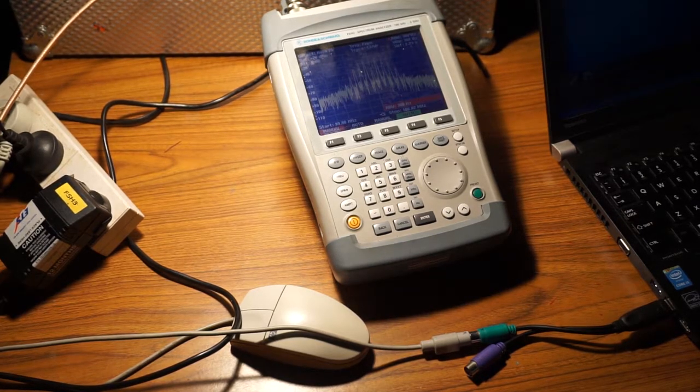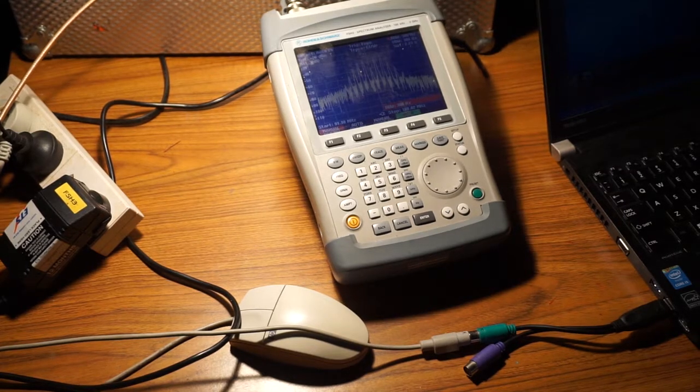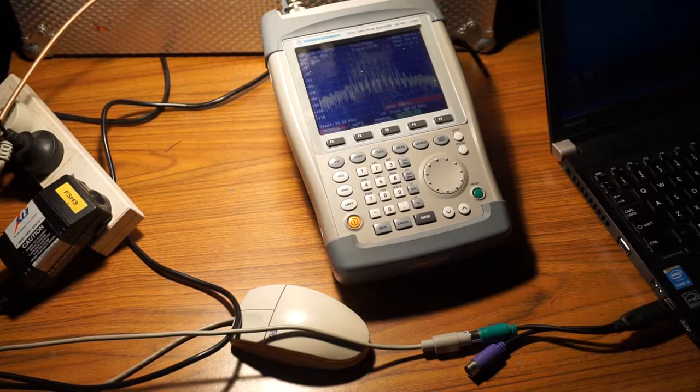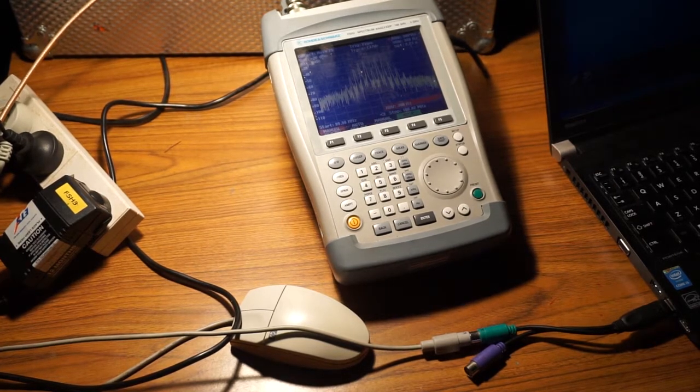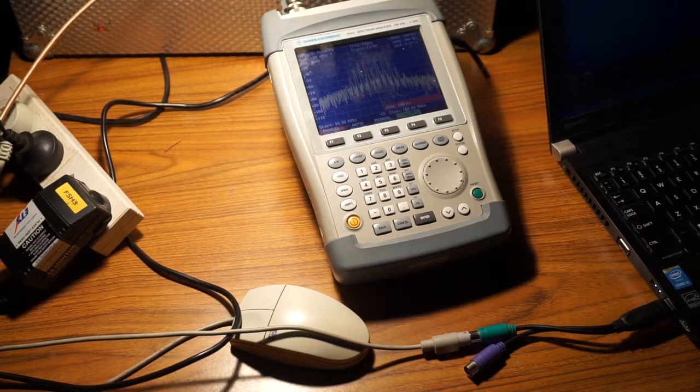So what we're looking at here, I've changed the modulation to FM. So this is in fact an FM signal, and we can see the carrier has now dropped right down. We can see these other, what I call Bessel functions, or the other sidebands there, but the carrier has dropped down. So we learned about this. It seems such a strange thing with FM.